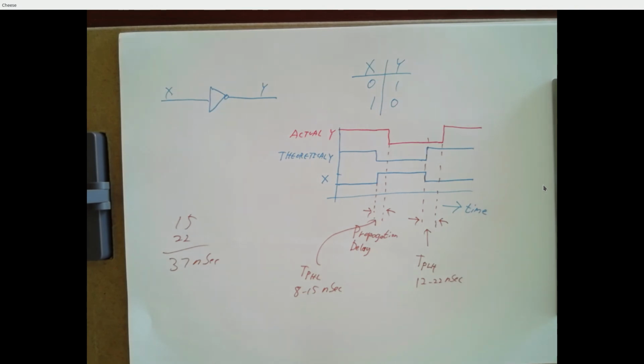Okay, so this is a long time. Now that's okay for us because mostly we've got an inverter, you flip a switch, it takes 22 nanoseconds for the LED to turn on, who cares, right? But as we start talking more about building computer circuits, things that have clocks and things that run continuously, you want to keep in mind this idea that there are propagation delays and we can ignore them less and less as we go forward.